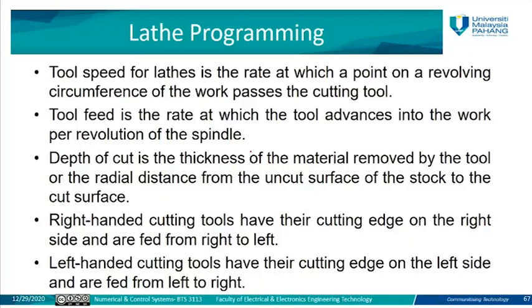We also need to define the feed rate and the speed here, and also the depth of cut on the thickness of the material. Since we are talking about cutting in the lathe case, there is a depth of cut on the material itself. Right-handed and left-handed cutting tools also have their cutting edge either on the left side or on the right side.